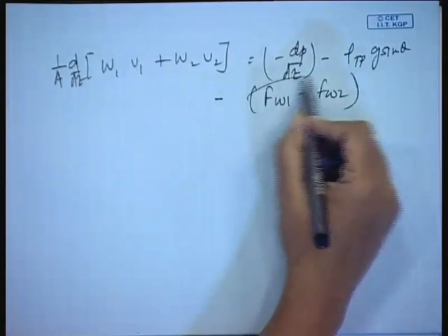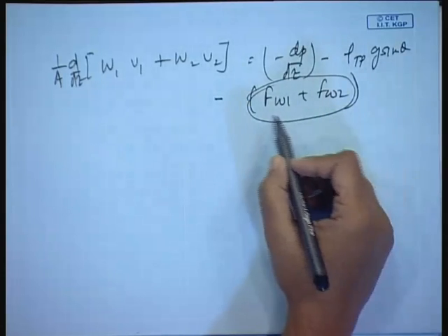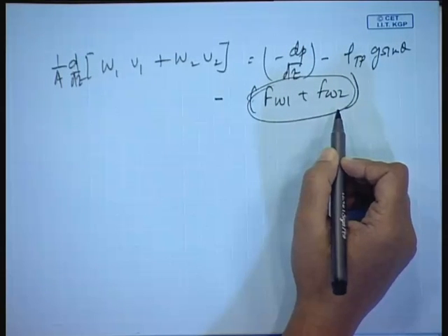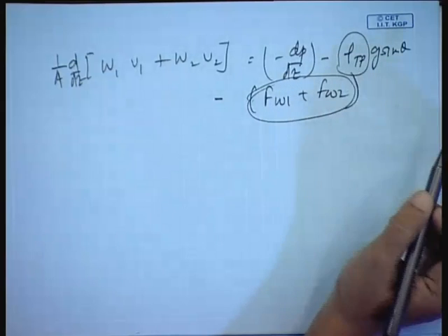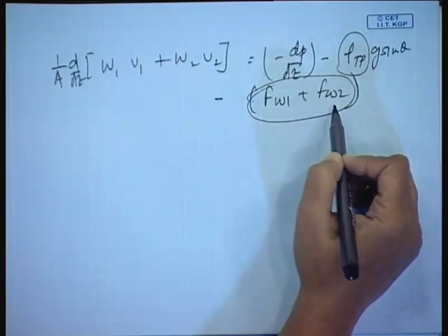What happens when there is mass transfer, what happens when there is phase change, those things we have already discussed. In the next class, we will try to express the pressure gradient in terms of known input parameters, then we will find out the condition of choking. From this basic equation we find that to find the frictional pressure gradient term, we need to know how to express tau W1, tau W2, etc., and how to find alpha. Without alpha we cannot derive this term. There are certain empirical approaches, and we will proceed with those after this.